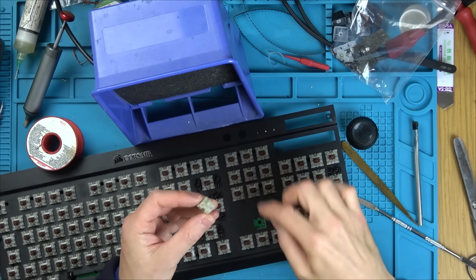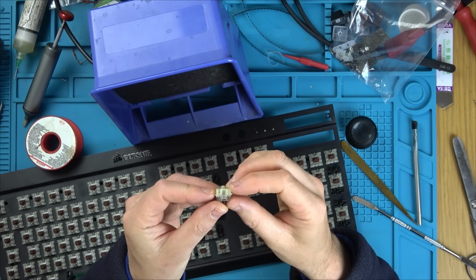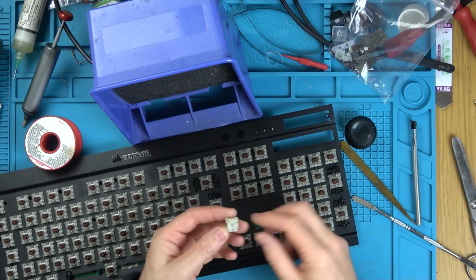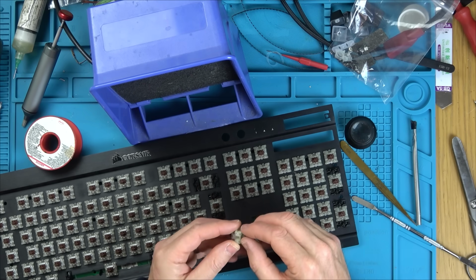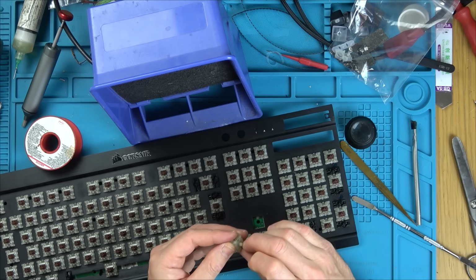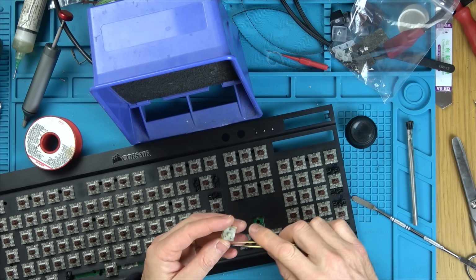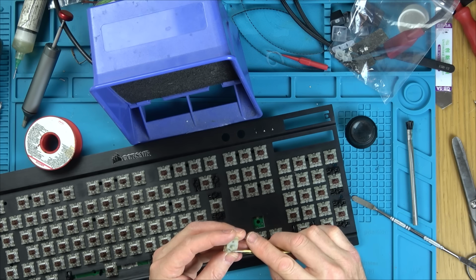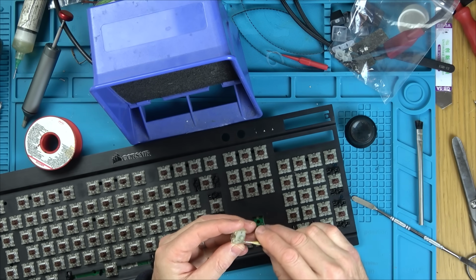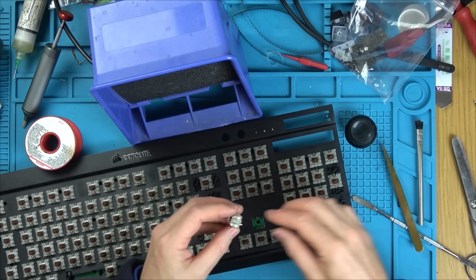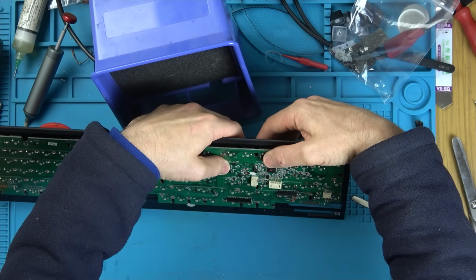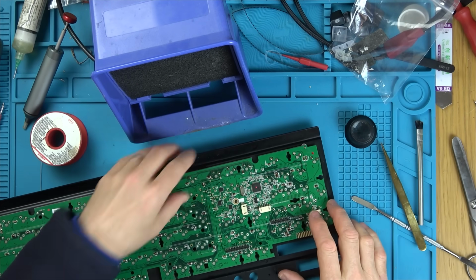Now just quickly, if I can't find one of the legs, like this one here, bent over so I couldn't solder it, then what you can do is just unsolder the other leg, or if you haven't soldered it, then you don't need to do anything. You can prise it up from here, you see, because when I'm forcing down the PCB, there might be the odd leg that bends out of the way rather than goes through the hole. But there you go, you can see now that that's upright. So that should go through the hole. Boom! And we're through the hole there now.